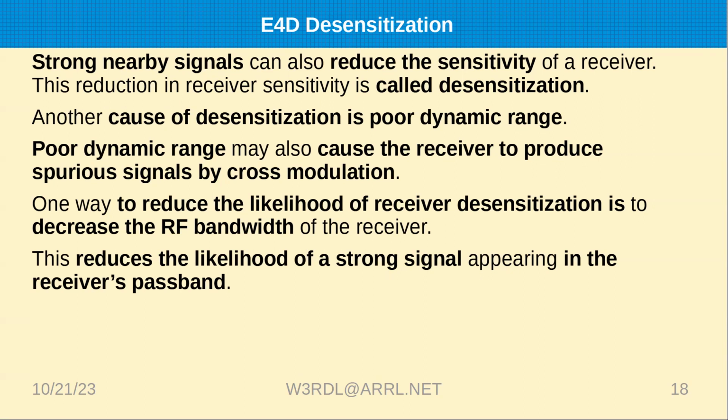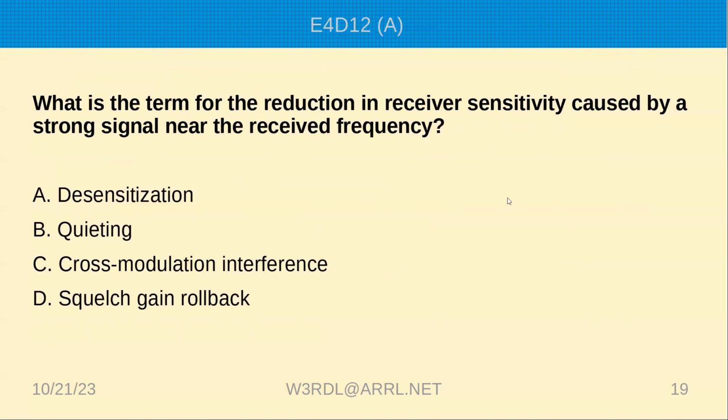Yeah, there's times I get like a nulling effect and I have no idea where it's coming from because I don't see any signal nearby. It's like dark matter, somebody next door that's got a transmitter, just wiping everything out. I don't know. But one of the things you can do is decrease the RF bandwidth, which means you put your filter or pre-selector or whatever on. And it might reduce the signal enough that you stop having that effect.